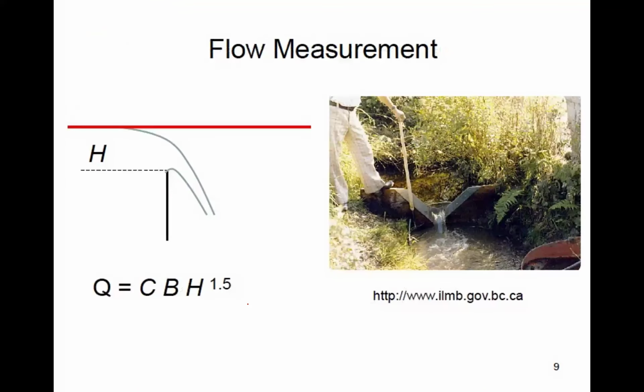Now, we mentioned that one application of these structures, weirs, is to measure flow, really. In this image, we have a V-notch, very, very common for measuring flow. So what happens is, if you measure depth upstream above the crest, that is your total head. You plug it into this equation, everything else is available or measurable, like width. And if you have a good estimate of C, then you can calculate discharge. And what is typically done is, obviously, as H or depth changes, discharge changes.